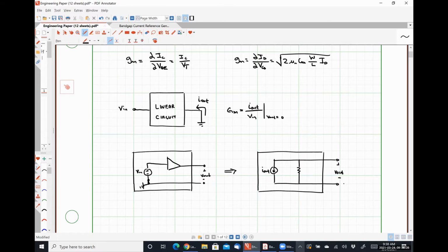Now, when we have our original circuit open circuited, and we're trying to find its equivalent resistance, or Thevenin resistance, or Norton resistance, or whatever you want to call it, what do we do to V in again? When we're trying to find the Thevenin resistance directly, we have to turn off all of our independent voltage sources, so we would short it out.